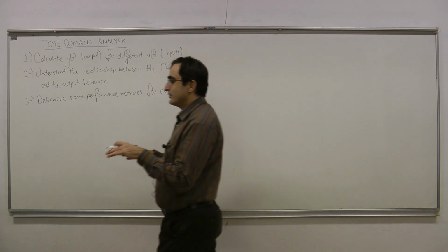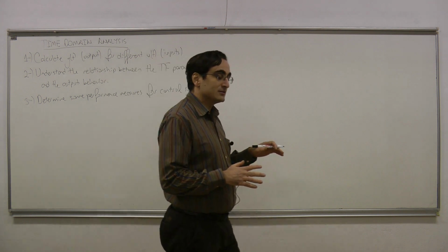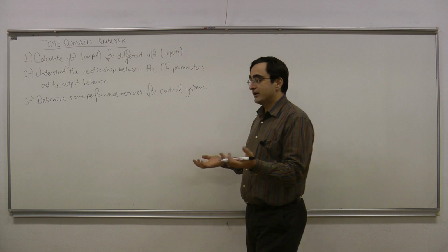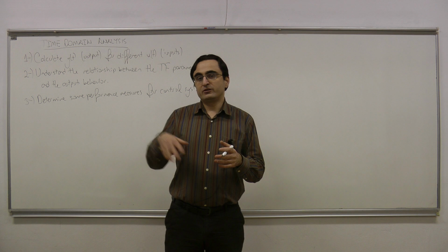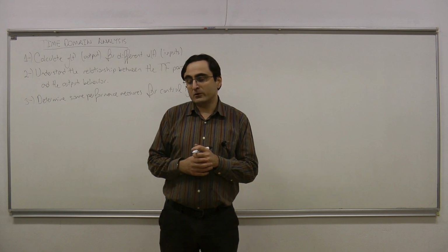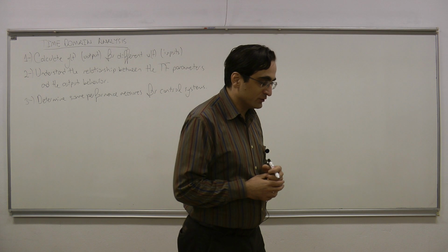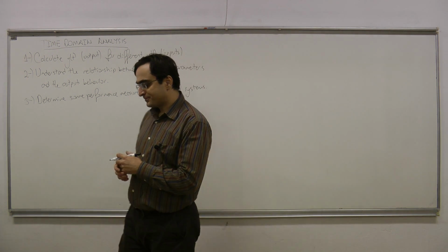So suppose that it's now 20 degrees, and suppose that I want it to be at 27 degrees. And if the air conditioner really takes 2 hours or 2 days to be able to reach the desired temperature value, then I would say that that air conditioner is really a bad air conditioner, because its settling time is really too large.